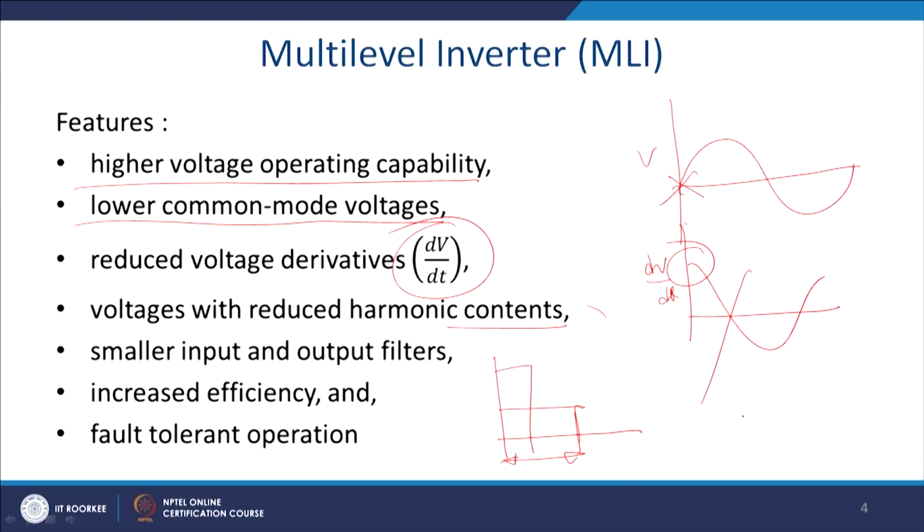Instead of that, let us take a whiteboard. If you have a multi-level inverter where you can apply 50 volt as well as 100 volt, then if you require 42 volt, you will be applying 50 volt for these durations, and thus you will have a very close area, this area and this area, and the instantaneous difference of the voltage will be very small, and for this reason definitely you will have the least harmonics.